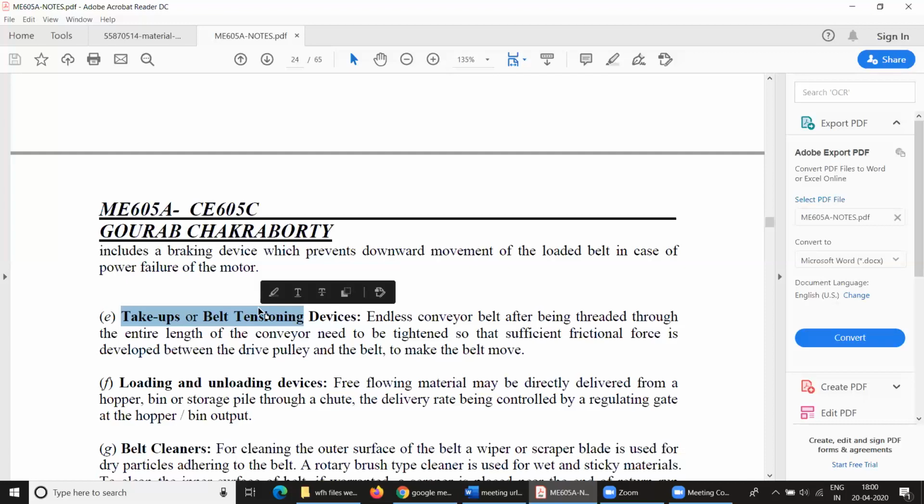Now, for discharging at any point along the length of a conveyor, a plow or belt tripper is used. I will discuss later what a belt tripper is. A plow consists of a rubber tipped blade extending across the belt at an angle, maybe 60°. A plow may be one-sided discharge or a V-shaped blade for a two-side discharge.